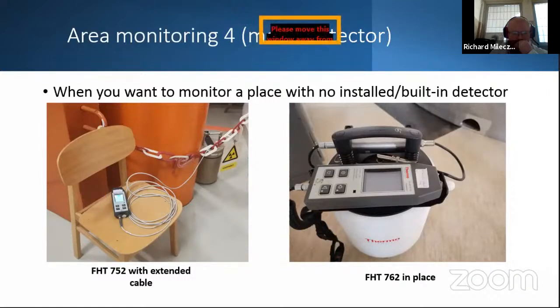For example, there are new regulations that require new measurements, or you have periodic measurements that were simply not thought of when the installation happened. Area monitoring systems rarely have a plug-and-play system in place. Therefore, you have to rely on portable detectors. These can be simple handheld devices with attachable detectors, or maybe just a simple detector. At any rate, you can place them down on the point of interest and do your measurements. If it is something that has to be left there on a semi-permanent basis, then you simply leave it there.